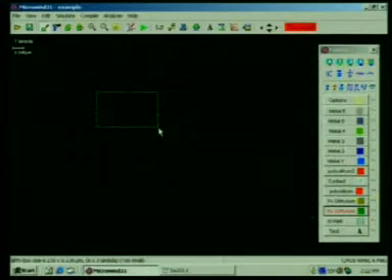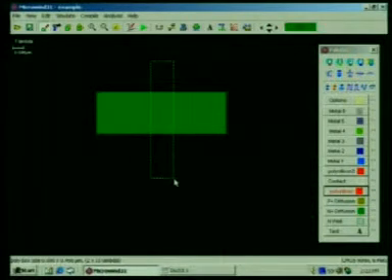I have already selected the technology file, this one. You can check out 90 nanometer technology. It supports up to 6 metal layers. So, there are 6 metal layers here, and then just click this, and the area should be at least 4 by 12, you can see at the left part, this much. After that, you need some polysilicon. I will select that one, and this should be at least 2 lambda.